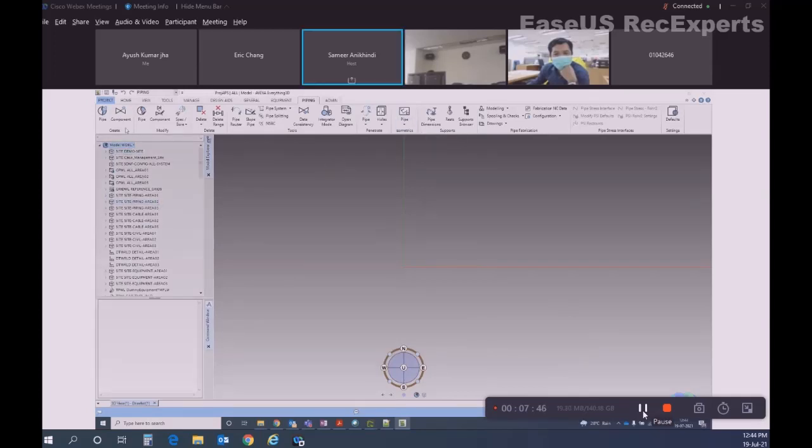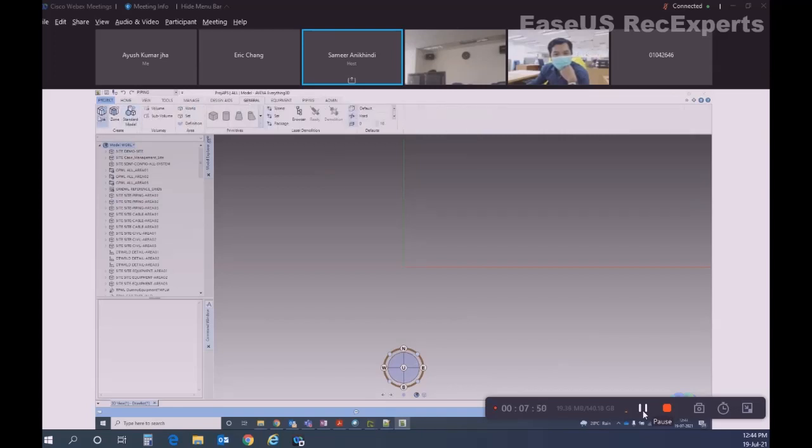Be at the world level, go to general. The first topmost element, as you know, for any kind of work is site and zone. First create a site. You can name it CTCI-training-site. There's a purpose here. You can select any of the purposes, but it is not compulsory. You can skip this for now.